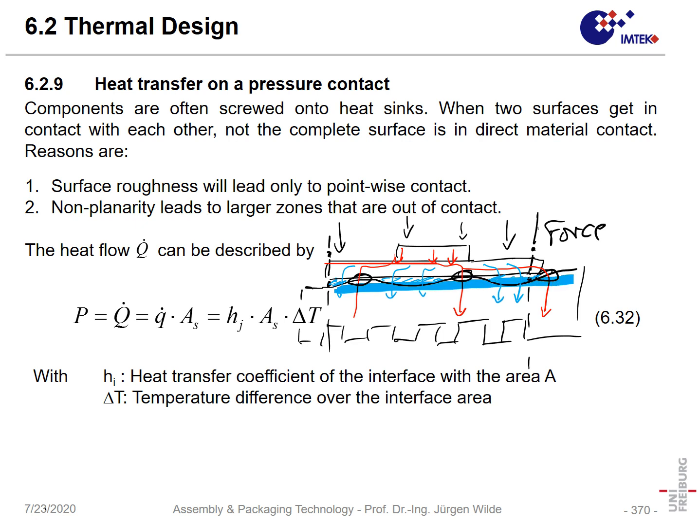which is something like that, a thick layer. That thermal grease would not be good, because a thick layer of thermal grease will increase the thermal resistance, and in that way we must use only a small amount of that additional material.